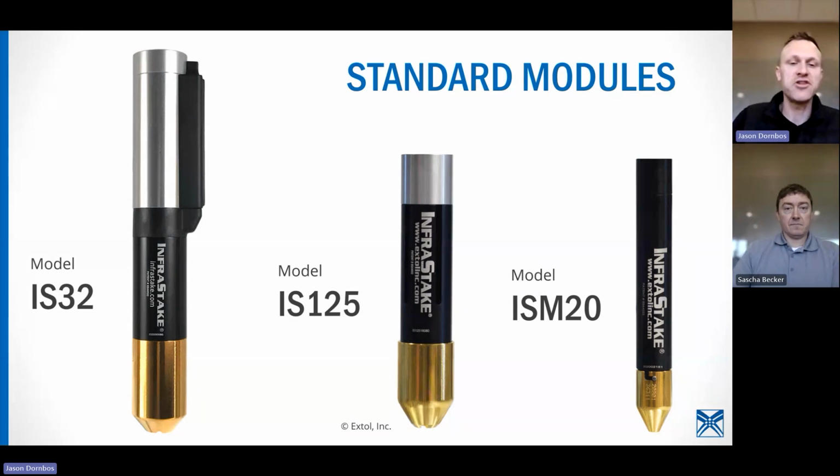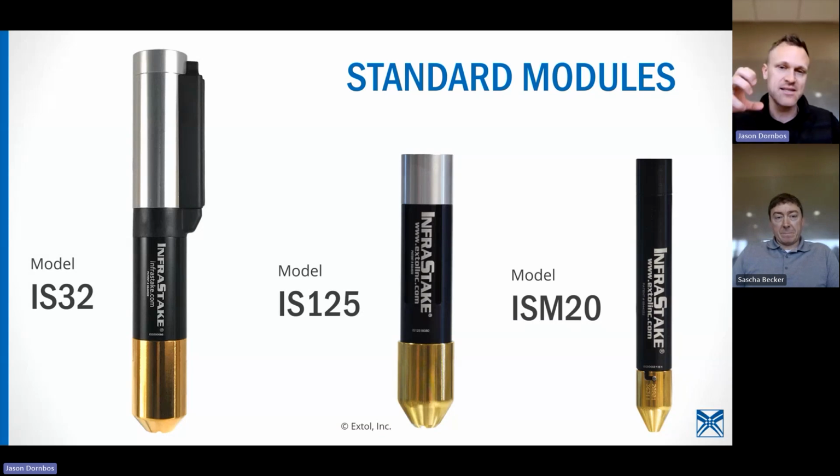So if you've done the validation to know that the strength out of that boss is what you need, because you've done tensile testing or other forms of testing to verify the quality of your parts, then in your machine, every single cycle, by monitoring some of these very simple parameters, you can know you're getting good parts because all of those things are adding up to a good part. I hope that answers your question.